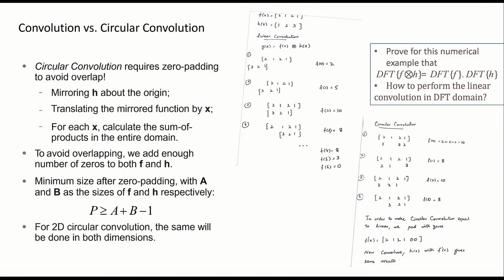Okay. So now this is circular convolution. However, our actual convolution is the linear convolution, not the circular. All the filters we design, we did not assume periodicity or circular convolution. We assume the linear convolution. So what can we do in this example in order to make it linear convolution? Now the padding comes up.